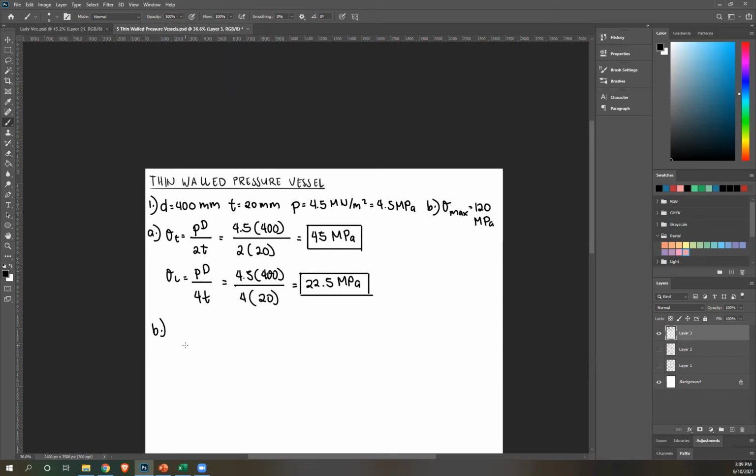For example, in our previous lecture, we solved for two forces, one for bearing stress, one for shearing stress, and whichever yields the least amount of force between the two, that is the allowable force. That is because we don't know which of the two is the critical force. It depends on the dimensions and properties of your material.